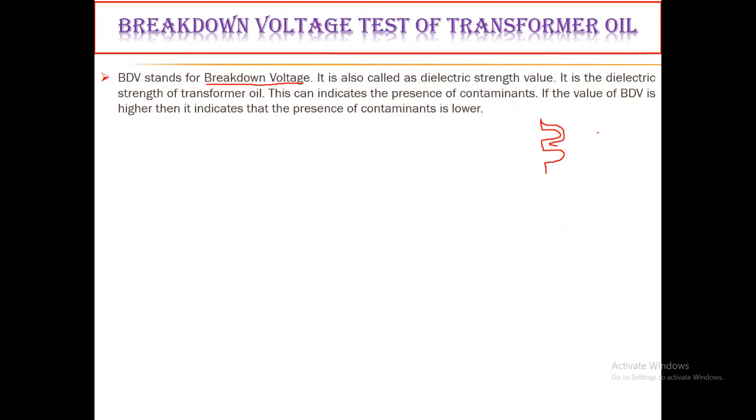This is about the solid, but if we consider a liquid dielectric where two electrodes are there, let us assume that this is the circuit breaker contact, and in between them is a liquid dielectric, or you can assume a gas as the insulation. In that case, during its opening operation under a faulty condition, the voltage across these two contacts at a certain distance will be higher than its withstanding capacity. As a result, it will produce a spark. So this is also known as a flashover. Sometimes instead of using BDV, engineers may say flashover voltage.